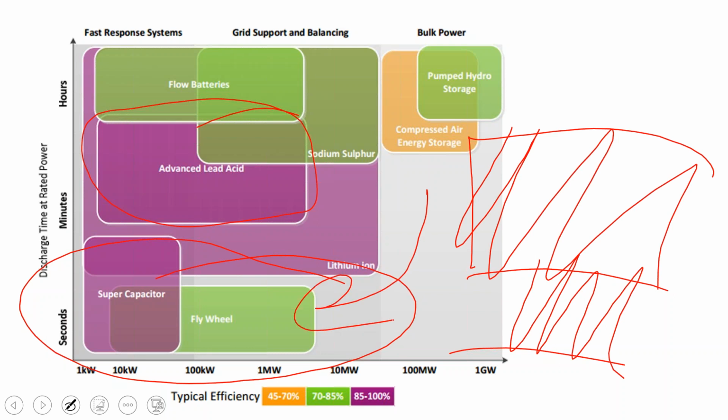And so what are flywheels and supercapacitors really useful for is energy storage systems like electric vehicle regenerative braking, or elevator systems where the elevators are climbing to the top of the building in a matter of seconds and then dropping back down to the first floor in a matter of seconds. That's where you get flywheels and capacitor systems into those kinds of designs, with lithium ion being particularly well suited for either maintenance-free batteries or commercial demand management, and then lead acid still being kind of the battery of choice for the off-grid market.